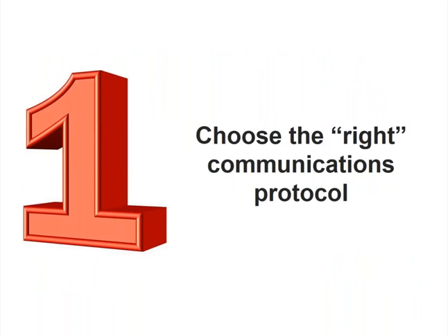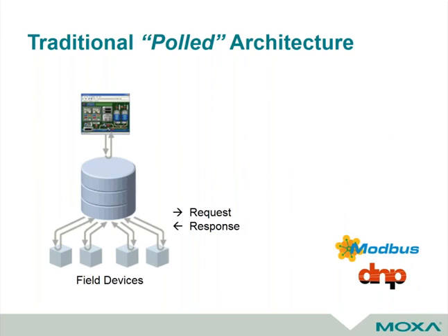But particularly in the new design stage, when you're doing an upgrade to an existing system or embarking on a new project, you really should spend some time thinking about what the means for communication is that we're going to try to standardize on. So I characterize this as choose the right communications protocol. In our experience, most of you are probably using Modbus. It's really been the de facto communication standard on the plant floor, across the campus, and even wide area networking has been very popular.